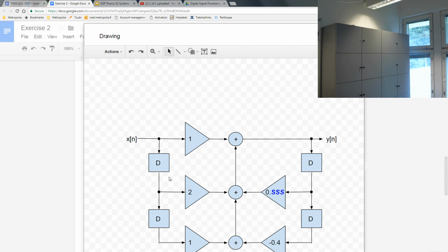Then you do the transfer function by moving the feedback terms to the other side of the equation, and that's where you usually make the small error on the sign. Okay, but with that warning, you should be able to avoid that. So basically, on that system, you would have a couple of terms here. Move it on the other side, then you will have A0, A1, A2.